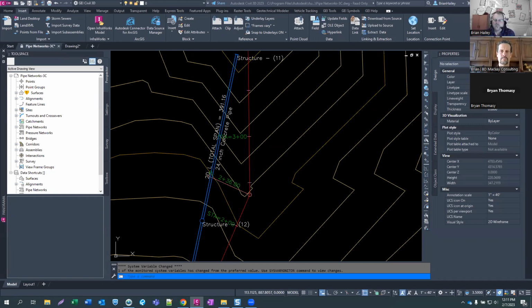Just remember, every time you pull a data reference, it has to open that drawing to verify that data reference, and then it closes the drawing, and if there's another data reference that has to go to it, it'll reopen the drawing. That's why it's taking so long to open. If you have a drawing data referencing 5 items from that one drawing, it is opening and closing that thing 5 times. And I guarantee you've got existing surface and proposed surface in there. Oh my God, that thing's got to be a couple hundred meg.